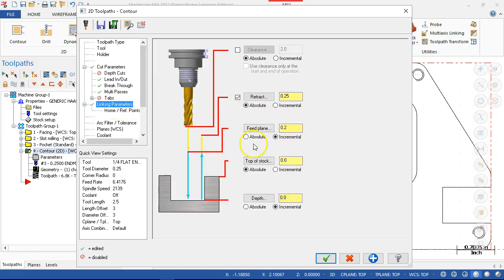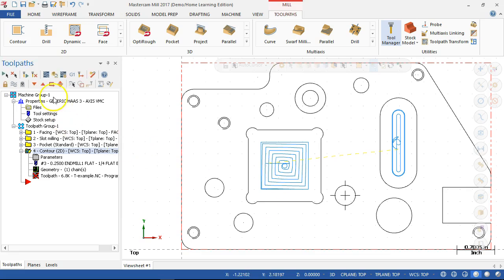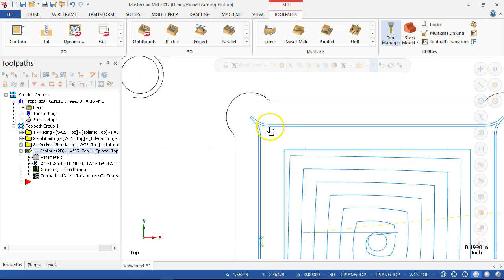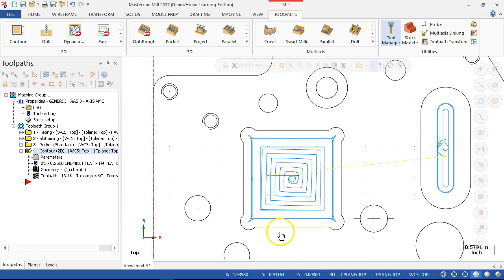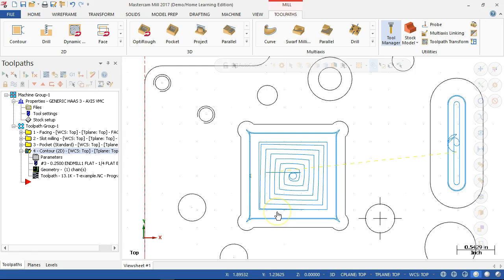And then the linking parameters. And we'll go ahead and accept and regenerate 30 toolpaths. All right, so first 10 thousandths pass, slightly lighter. Second one, heavier, goes completely into the corner. Until I see what the survivability of that tool is going full into the corner, I'm going to take that second pass.